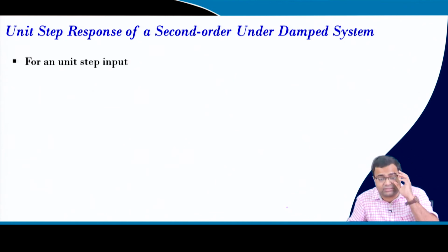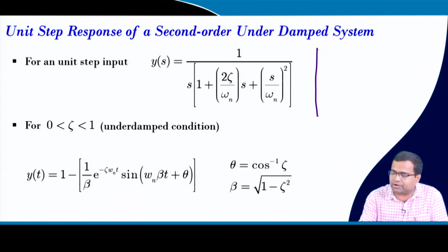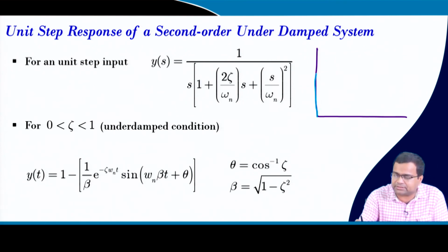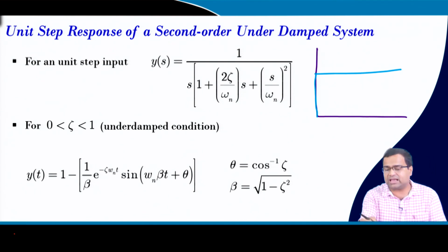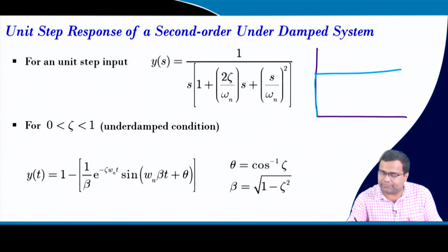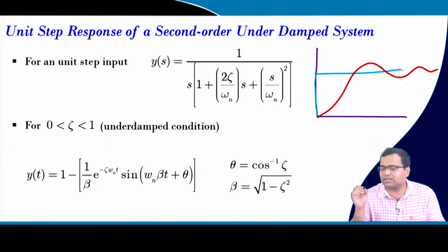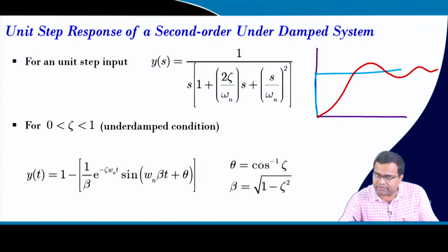Similarly, if you take the second order system response, then you can find out depending upon the damping ratio. You can draw the plot, we have studied this in the control system context. If you apply a step response, if K_DC equal to 1, here it is a unity gain, then you will find that, like this, and if it is even more overdamped, then like this.